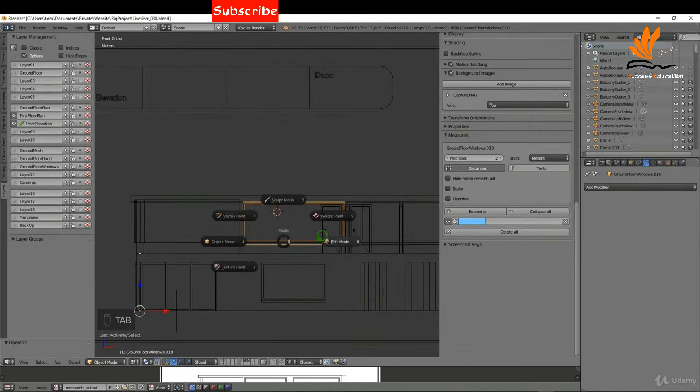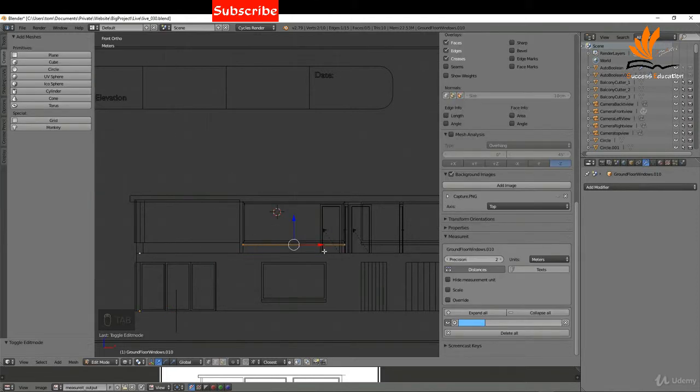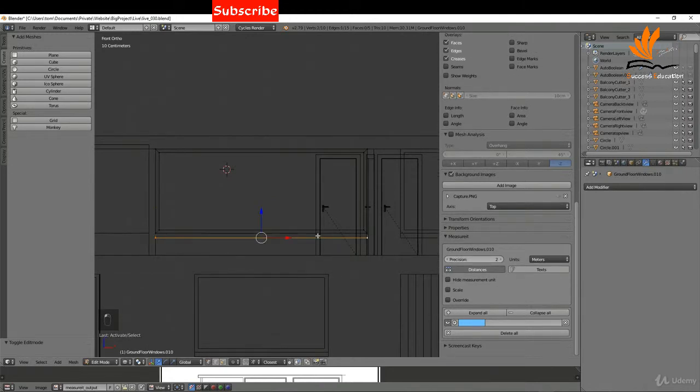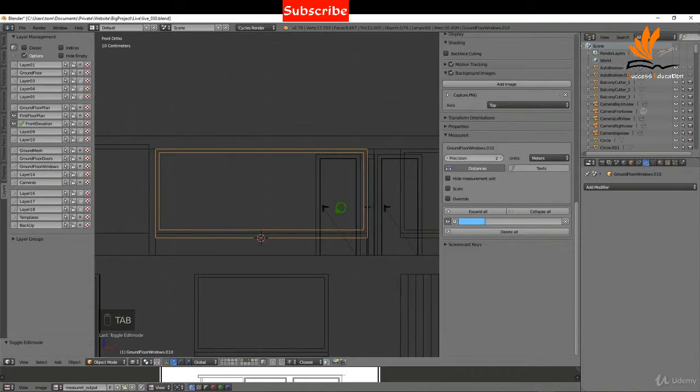Okay, so with this selected, I'm just going to tab into edit mode. Okay, and I can select 2 points here. So I guess I can select these 2 points, Shift S and cursor to selected. I'm just going to tab back to object mode.